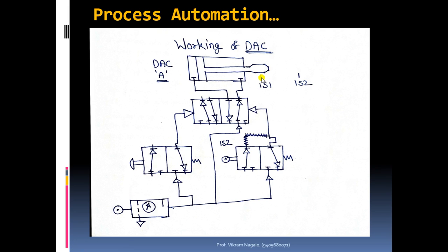And whenever this rod end is leaving this 1S2 position, the limit switch present at 1S2 will get unpressed, and as this is getting unpressed, the roller lever is released, there is no pressure on the left hand side, hence because of the spring the right side block will get active,